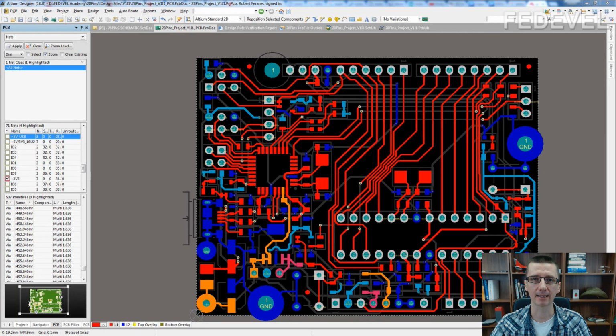Even though we electrically connected all the pins, it doesn't mean the PCB is done. We are going to do a couple of more things. We are going to improve the tracks, especially the power tracks. They need to be wider. We need to create the power planes, and also we will make it nicer. You can see by yourself it doesn't look really nice at this moment, and when someone takes your PCB, you would like them to say, wow, what a nice PCB.